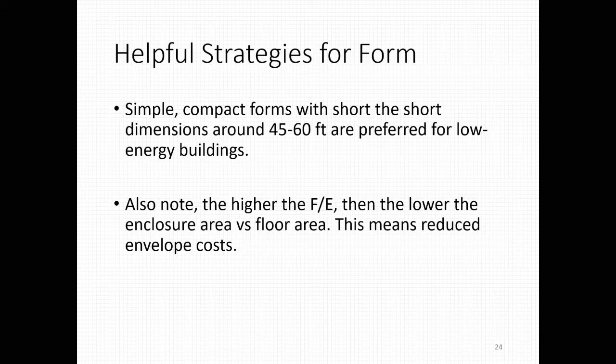But that's added cost. You have to insulate that stuff, and you have to condition it. You have to condition the air. You're not conditioning the air that goes up into those high ceilings, but the air you're trying to condition your occupied space with is going to go up there. So, it's going to increase the cost.